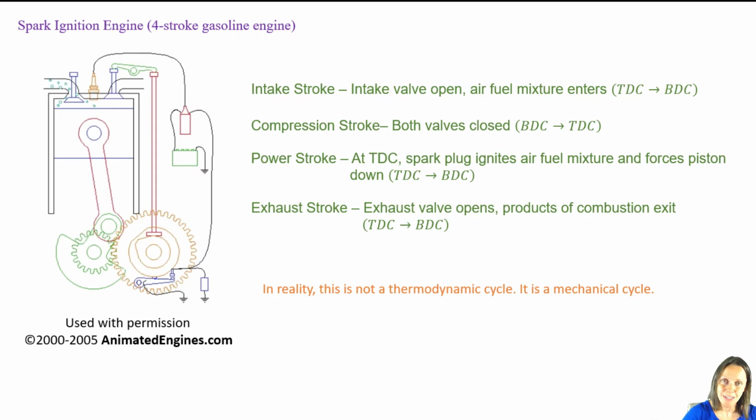So it's not a true thermodynamic cycle, because what you start with in the first process is air and fuel, and what you end up with during the exhaust stroke are the products of combustion. If you're combusting a hydrocarbon fuel with air, you'll get CO2, you'll get water, you'll get nitrogen, you'll get some other stuff as well. So it's not a true thermodynamic cycle, because the state at state 1 is not the state at the final state, right? Because you've got completely different substances. But it is something that we can model as a thermodynamic cycle.